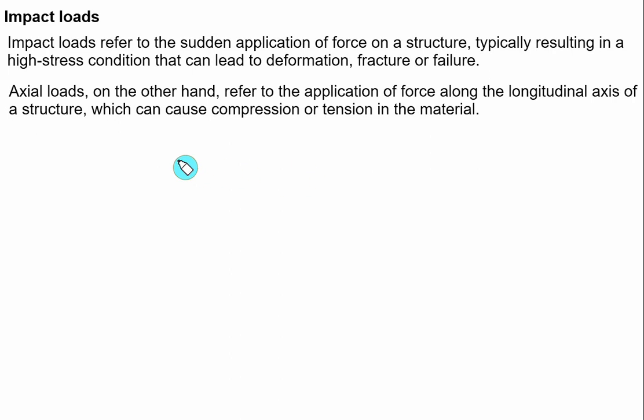Up till now we have done the axial load, in which the force is applied through the longitudinal axis. Because of this, axial loads can cause either compression or tension in the material. So when the impact load is applied axially, the effect on the structure will depend on the magnitude, duration and direction of the force. If the force is large enough, it causes the material to yield, deform or fracture.